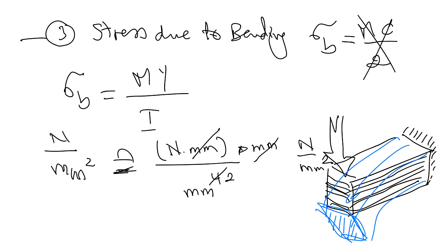view. Here is the new location of the beam after it bends. We all agreed now that the upper layer got extended, which means that it is subjected to tension stress, which means all the points on that layer have a positive stress. And we also agreed that the lower layer got contracted. The only way for this layer to get contracted is to be subjected to compression stress, right?